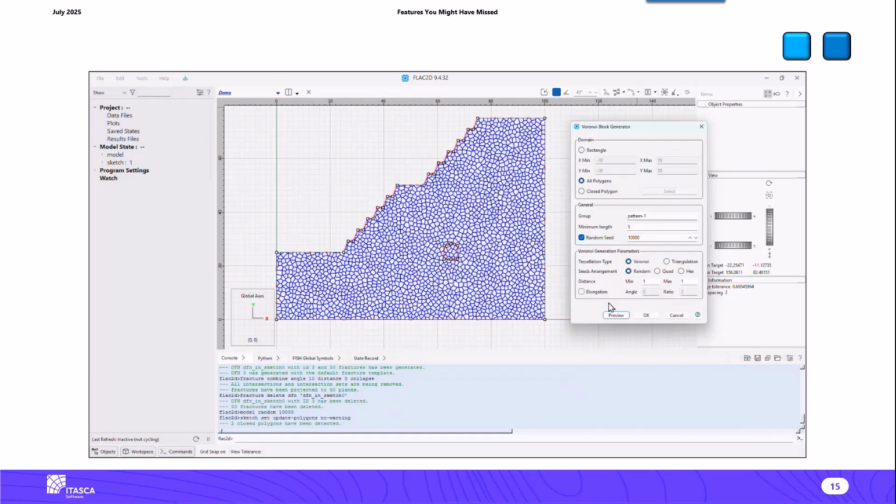So by representing the rock mass as a series of Voronois, what we can do is specify different properties along the edges of those blocks, if you will, and then we can zone them as well, and then have a different set of properties in the zoned material. In this way, we can initiate fractures and grow fractures in this type of material. This is essentially what we would refer to in UDEC or 3DEC as a bonded block model.